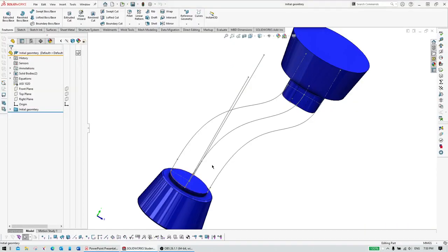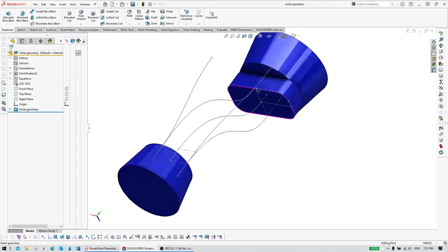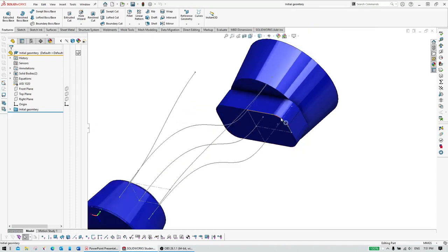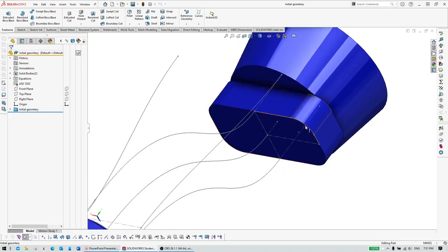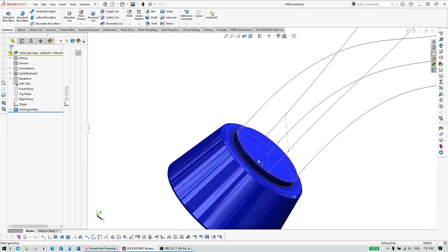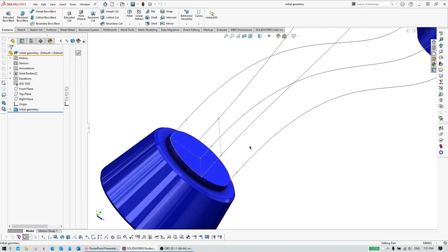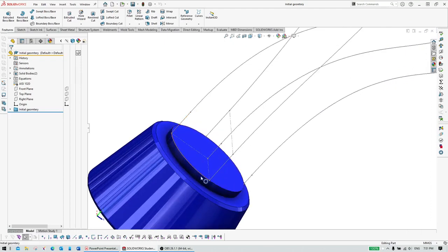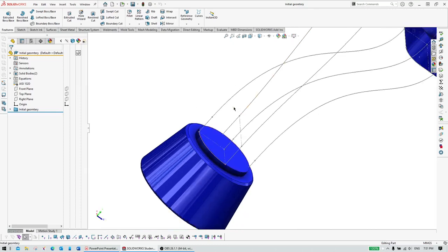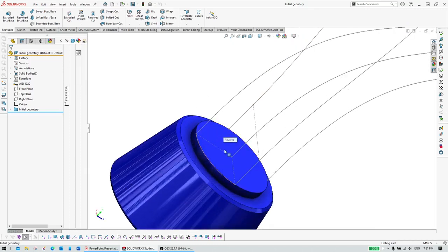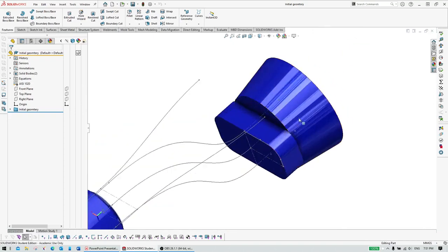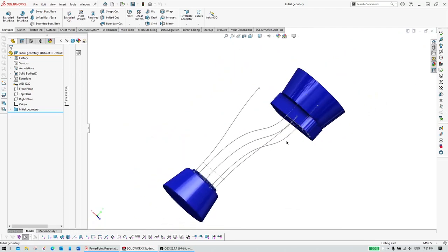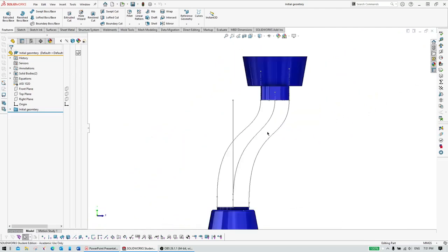Okay, let's get started. And as you see, for a lofted surface, I need two types of cross section, right? As a feature, you need a cross section, but in a surface, you might need just a line. Okay, I have this line, and since lofted surfaces have limitations, I need to create just a half surface, as you see. And I just need to create this line. I have already added these sketches just to save time, and I have added a sketch over here, and I have some helper surfaces on this side.